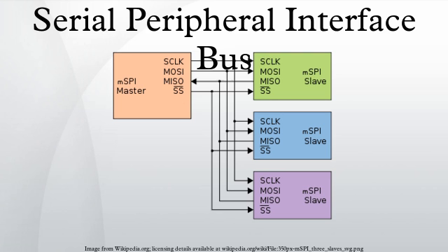SPI protocol being a de facto standard, some SPI host adapters also have the ability of supporting other protocols beyond the traditional 4 wires SPI. Examples of SPI adapters: protocol analyzers. SPI protocol analyzers are tools which sample an SPI bus and decode the electrical signals to provide a higher-level view of the data being transmitted on a specific bus.